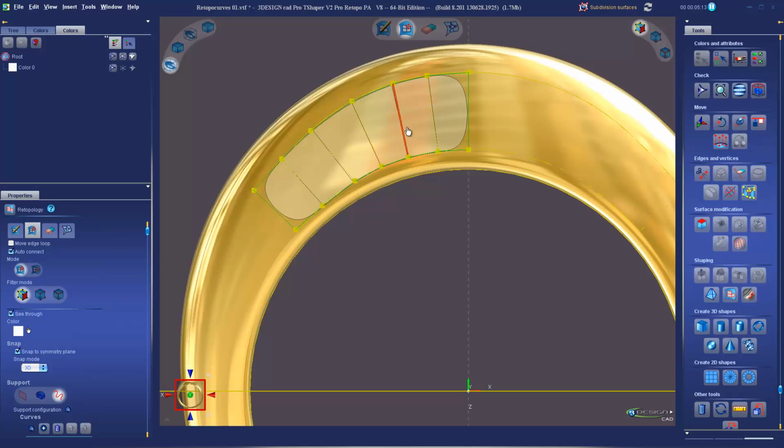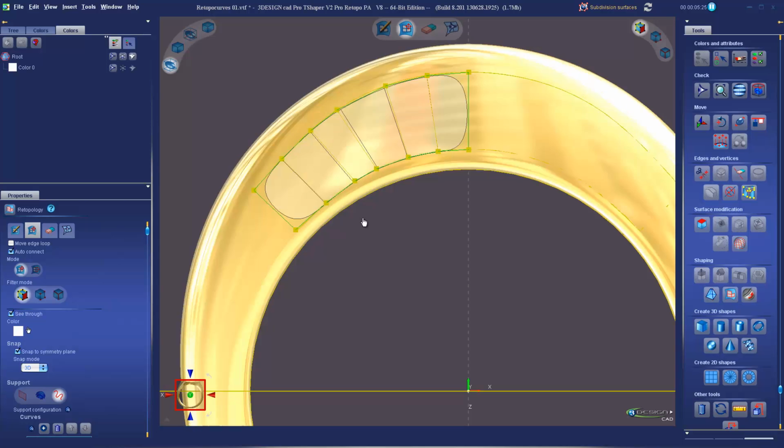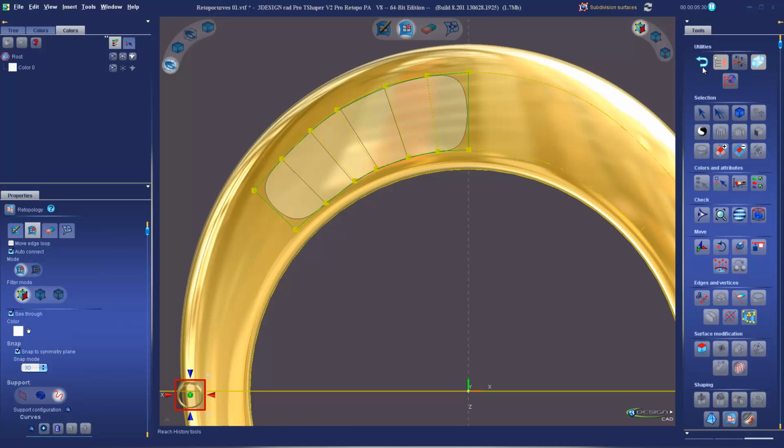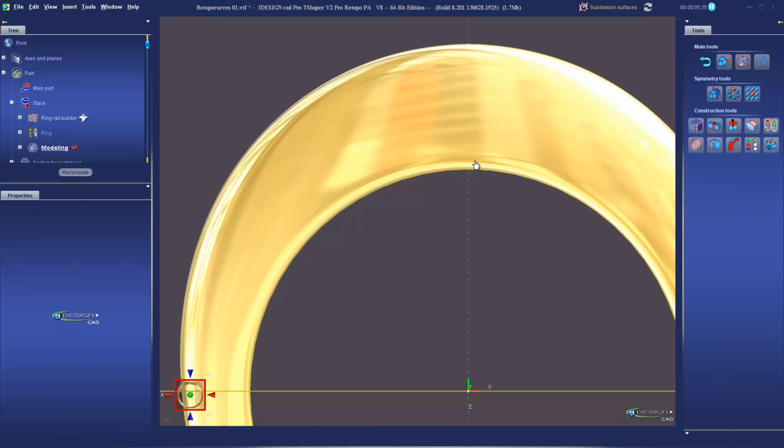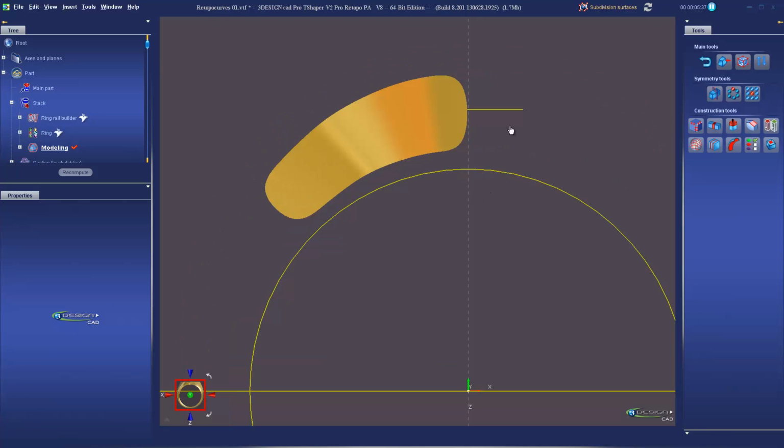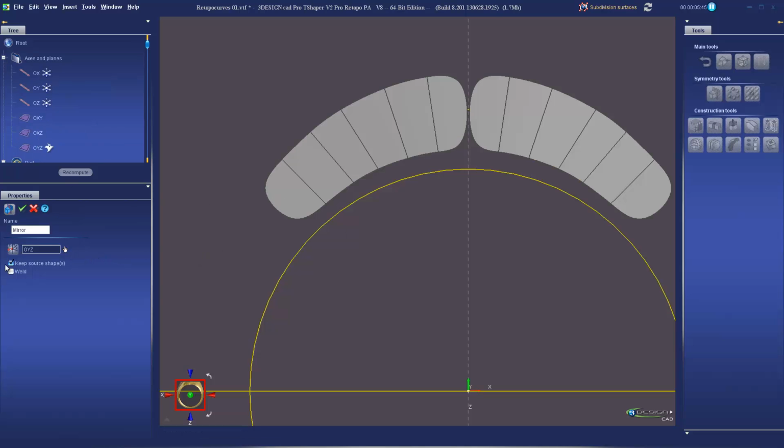Try to make these as even and neat as possible so we get a nice even pattern in here. Something like that. Now this is a symmetrical ring, so I can just do half of it and then mirror it over using symmetry. So I'll go ahead and do that. If I back out of Shaper one level to our sub level, hide this ring for a bit so we can see. We'll add a mirror. Choose the correct plane and weld it all together.